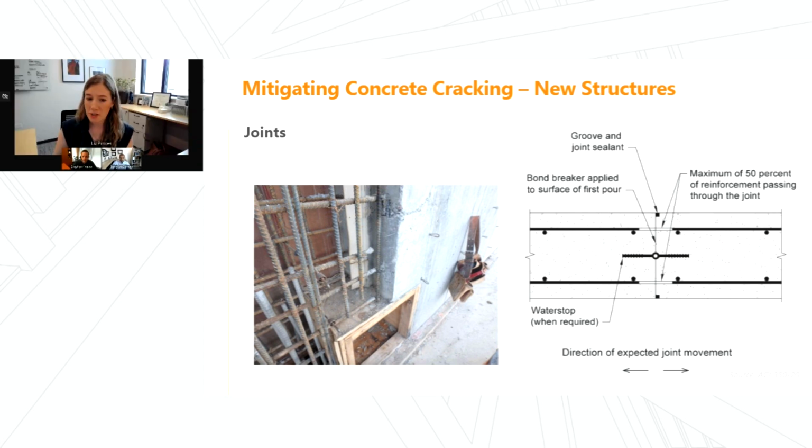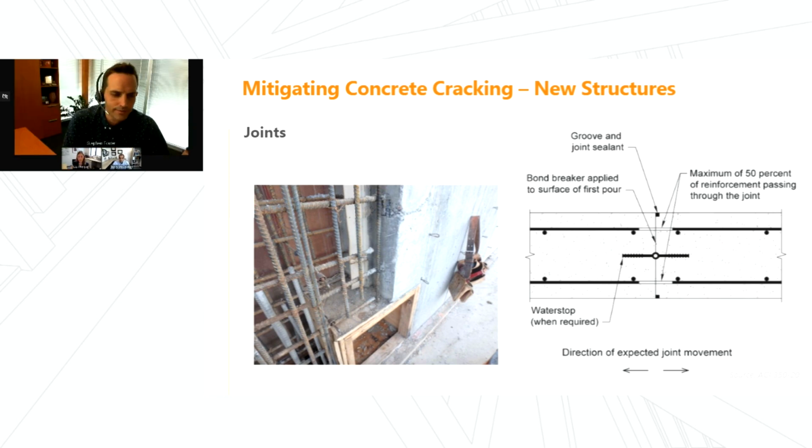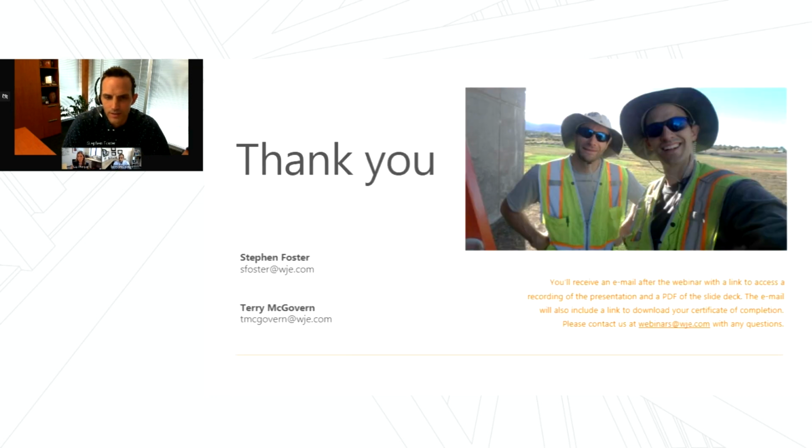Okay, how beneficial is installing zinc anode in new construction as compared to during repairs? Yeah, most commonly it's done during repairs on existing structures. In real aggressive environments, you might install something on the front end. And I didn't cover impressed current cathodic protection, which is not just relying on the galvanic difference between zinc and steel, but actually uses a power supply to provide protection. In really extreme scenarios, maybe something like that might be done.